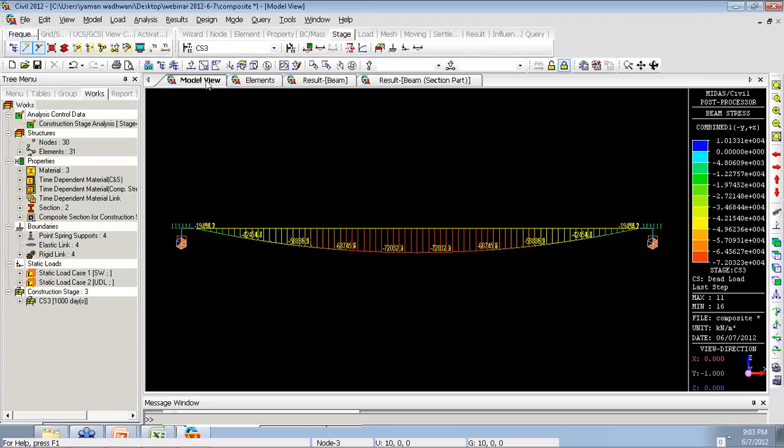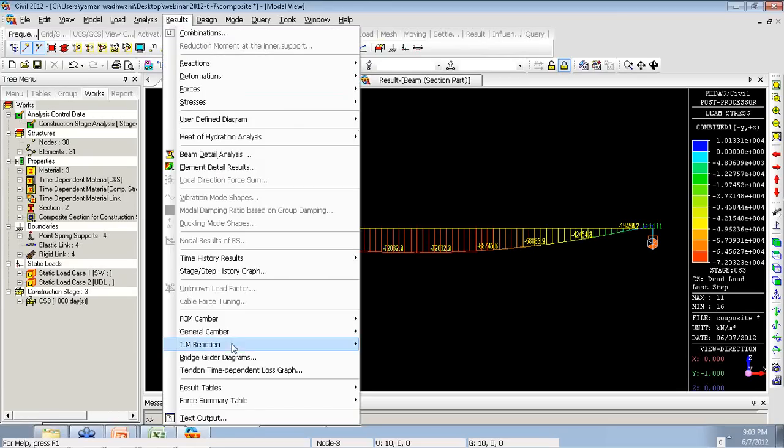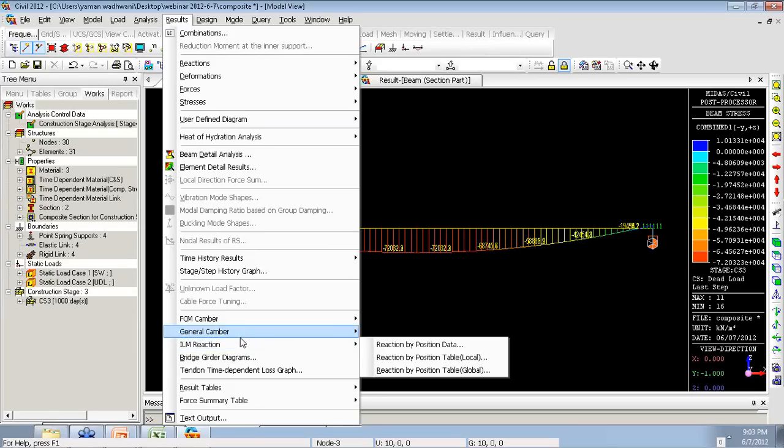This is useful for doing the elastic stress limit check at each construction stage, because there will be changes in stress distribution when we activate the composite slab, so it is necessary that the stresses fall under the elastic limit before and after composite.